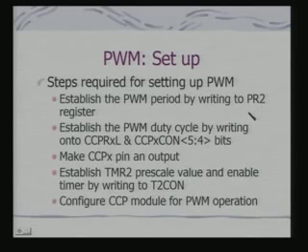The steps required: establish the PWM period by writing to the PR2 register, because I have shown you that when I do the comparison, that comparison would take care of the period requirement of the PWM waveform. Establish the PWM duty cycle by writing onto these two bits.